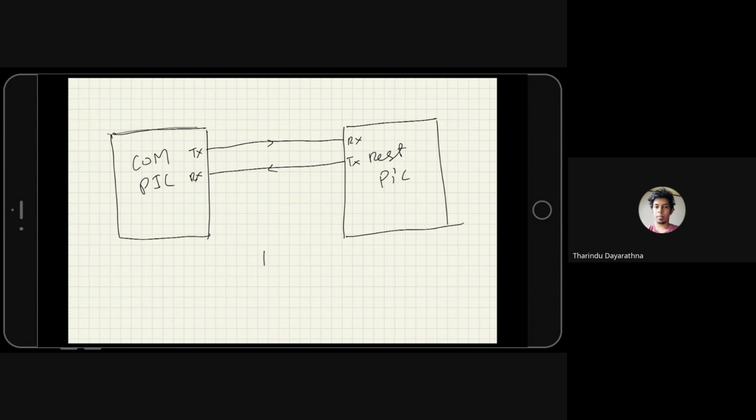not sometime, always. So UART is normally high. If you draw a plot, the UART TX line is normally high. That is actually 3.3. When there's data, it does some flipping, like this kind of signal, and goes back to 3.3 again. Okay. So there is some problem in this peak actually.